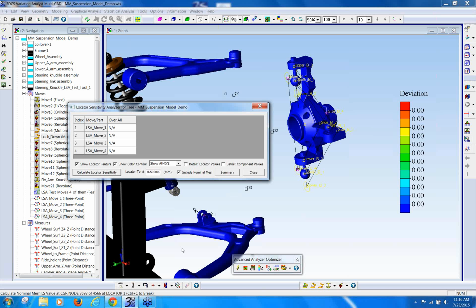As I'm trying to fill the time while this is calculating, you can see this is the calculation time for just a knuckle. And this knuckle has got some data to it, so the mesh on it could be quite dense. The more parts you have and the denser the mesh you have, the longer this is going to take.